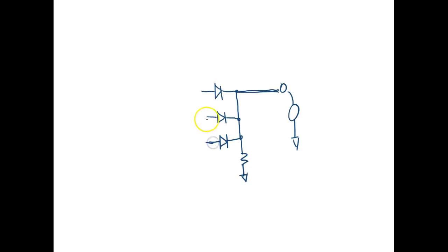And what we're gonna do, of course, over here we'll put 5 volts or we'll put 0 volts. And 0 volts is not a nothing. 0 volts is a ground, right? Or common. Okay. And we're gonna say 5 volts is going to equal a 1. Well, actually it's gonna be 4.3 because the diode's gonna drop 0.7 of a volt. And we'll say 0 volts would be equal to 0. Okay?